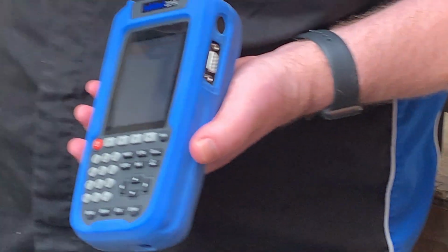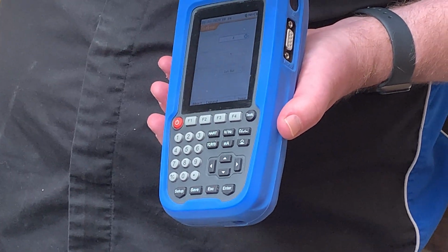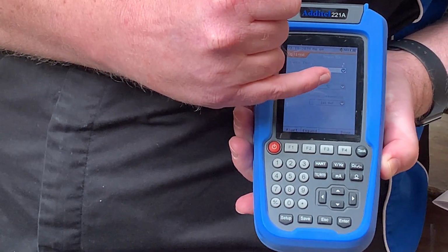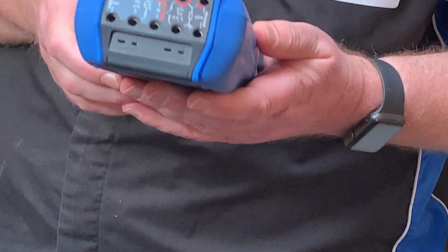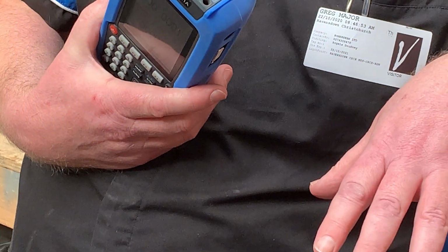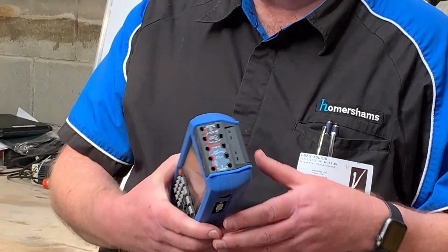And you also know that every thermometer has a cold junction reference within it. And that's what we're using here. So we're saying we're going to use the internal cold junction reference. And again, 99.99% of the time you will. But there might be a time if you were working in a particularly hot environment or something, you might want to use a separate one. I've never come across it, but you might.